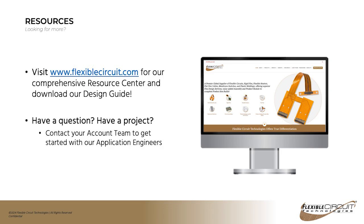That's a good question. If you are going to be bending your circuit sharply, you need to go with cover lay. Flexible solder mask doesn't mean that it's super flexible. It just means it's a whole lot better than the stuff you put on rigid boards. But it will crack if you bend it too sharply. So if you are going to be bending it sharply, you definitely want to go with cover lay.